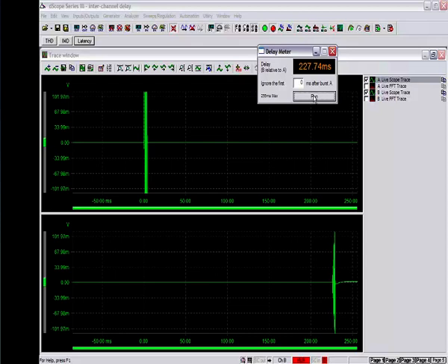So if we now switch this to aptX, where we've got a special low latency implementation here, we've got a latency now of 35 milliseconds, which is less than one video frame in either PAL or NTSC territories. This means that you can now use Bluetooth for audio-visual applications and gaming.